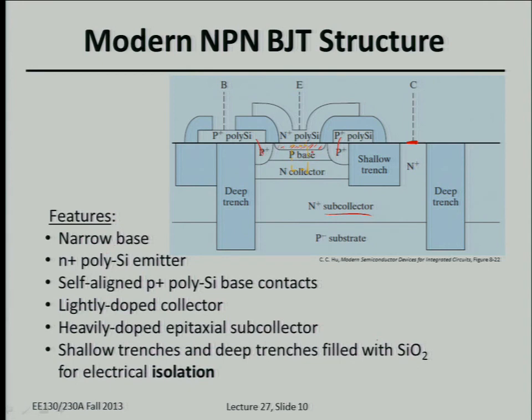So actually, for people who took 143, why would we want to diffuse dopants to form the base-emitter junction versus implanting and annealing? Less damage, that's right. So you don't have that non-ideal recombination-generation current. Diffusion is not damaging to the crystal. That's very good. Also, you might be able to better control the width of the quasi-neutral base region. Diffusion can be a slow process if you anneal at moderate temperature, so this quasi-neutral base width here can be more precisely controlled if you diffuse it.